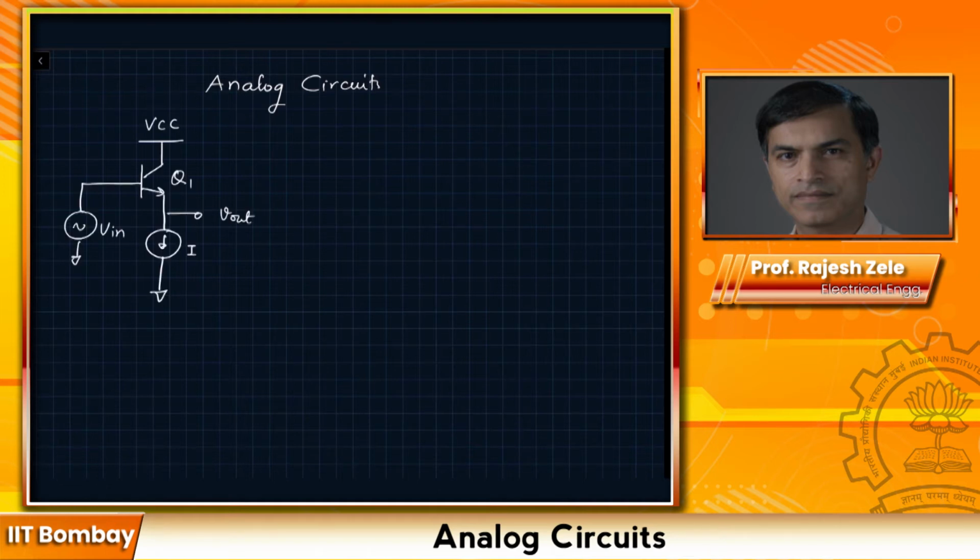So we already know that for this amplifier, V out over V in is equal to 1, and R out looking back in is equal to 1 divided by gm of the transistor. So this is a very simplistic representation of emitter follower or common collector amplifier. Now we will add more nuances to this circuit and understand the impact.